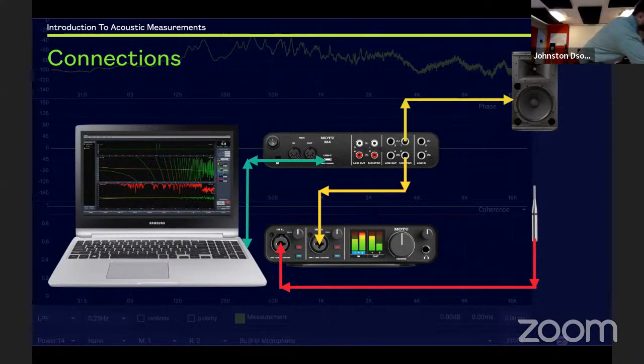No, you can't use the software loopback, because what has to be taken care of is also the time that is taken to process the data within the sound card, right? Because the D to A and A to D conversion will require some time. So that also needs to be taken care of.